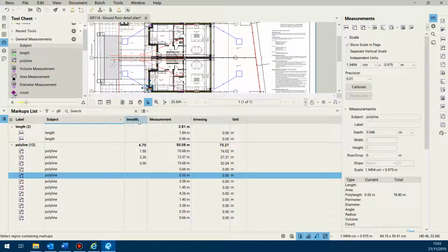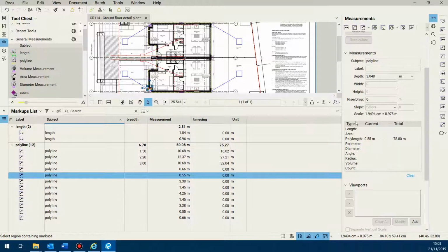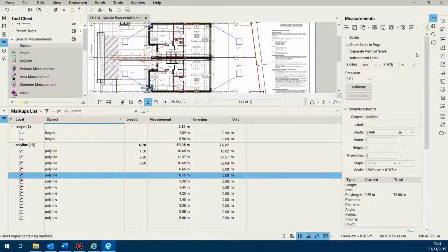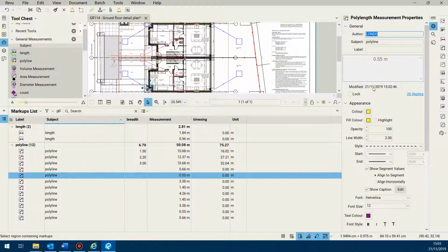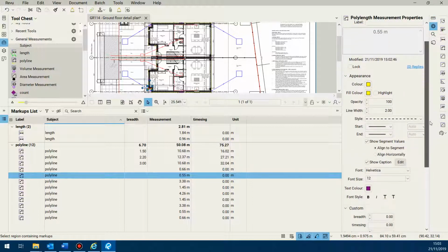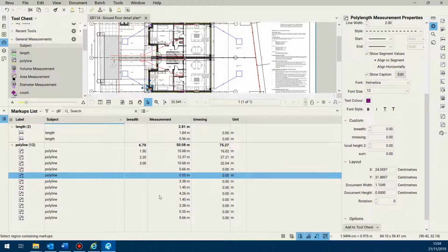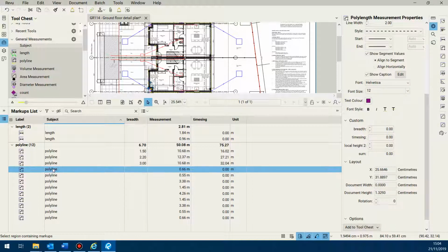Similarly, because we've created these columns, if you go into the properties of the polyline we're actually using, you'll see that dialog actually appears in there. And a little shortcut which is really beneficial, and bear this in mind: if you grab hold of the remaining polyline lengths that we haven't extended a breadth to, grab the first one and go to the last one holding the shift arrow.